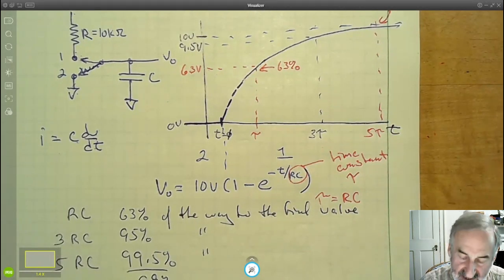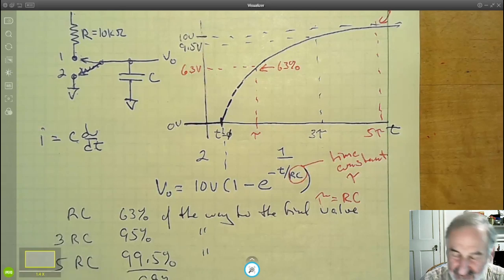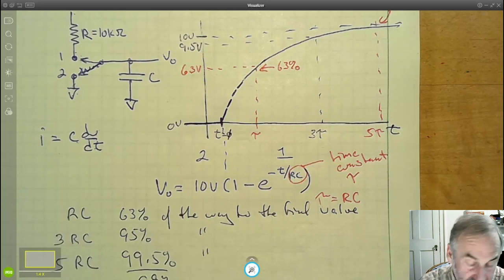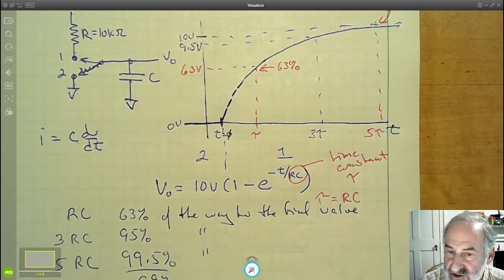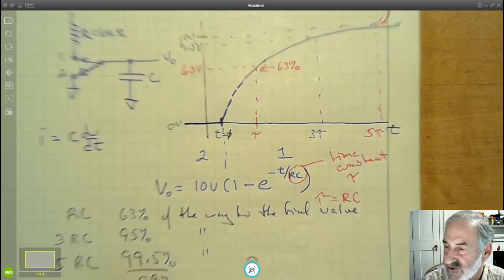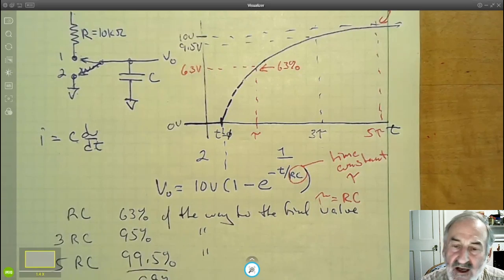So our capacitor charges to a final value. After 5RC, we essentially assume it's fully charged. And we can discharge it, we can change the voltage, but that's classic RC charging. And almost all the circuits you will see charge capacitors from resistors and not from current sources.